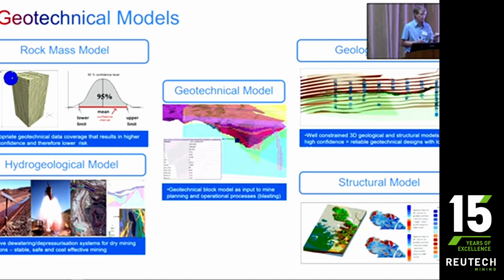Top left, you've got your rock mass model. You need to understand everything about the rock. That's our steel and concrete that we design in. We need to understand the strength of that material that we're going to mine in. You need to understand the geology, your lithological model. What is where in the sequence of where you're going to create the open pit or the underground excavation.